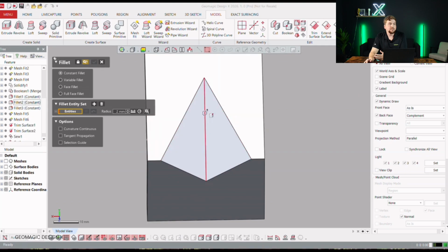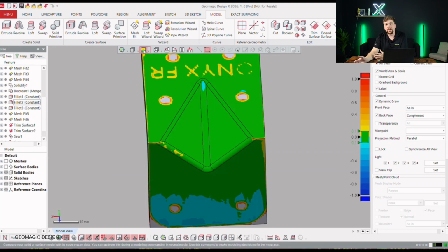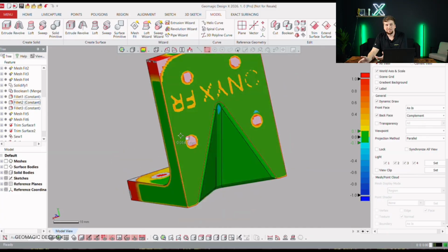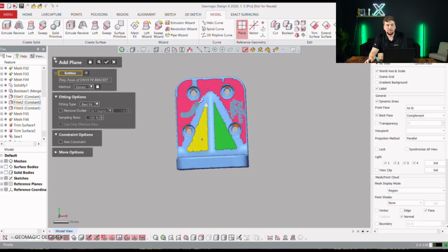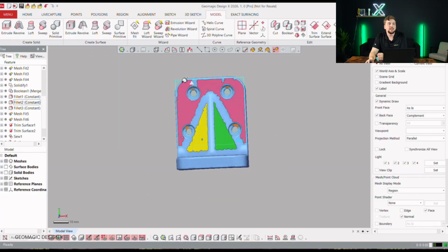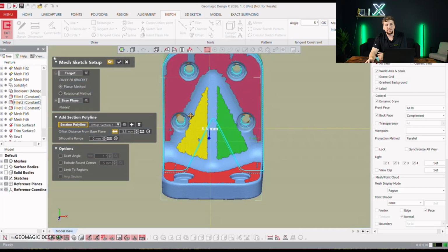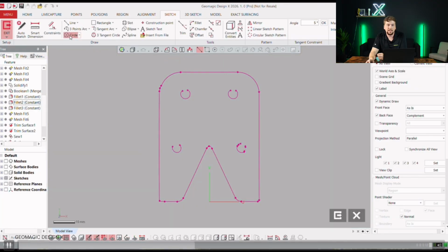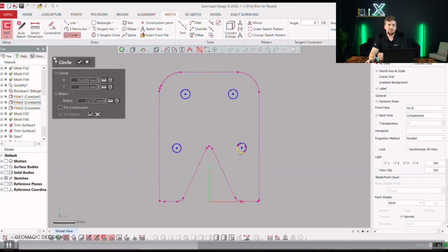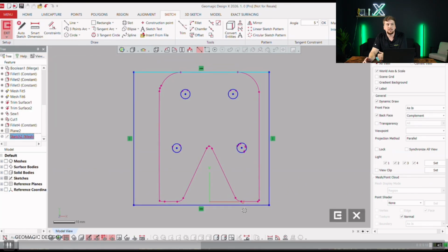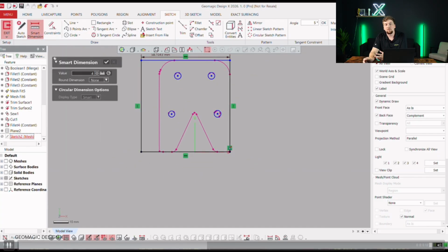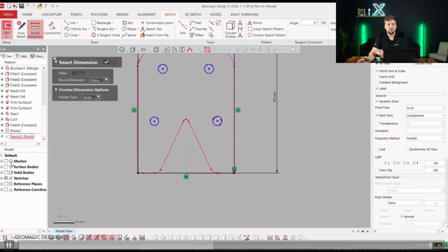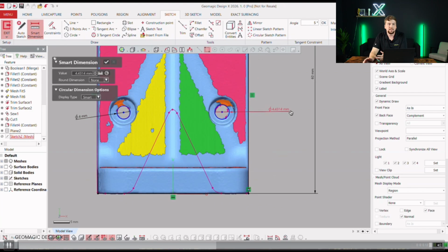Now, there's always going to be some level of deviation in your physical CAD model to the actual mesh data. That's because your CAD is your intended perfect world part. Now, as we're all familiar with, it's almost impossible to get an intended perfect world part. And that is what you're seeing here. As I keep turning on and off that analyzer tool there for the deviation, you can see that I'm changing maybe our radii to be a little bit smaller, a little bit bigger to conform to what the mesh data is, but I'm not trying to get it down to the 1 micron accuracy on this one. I'm still relying on those whole numbers of like 8 millimeters or 8.5 or anything like that.